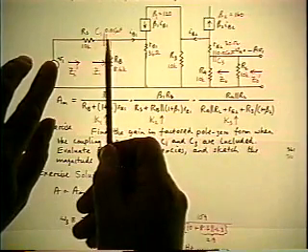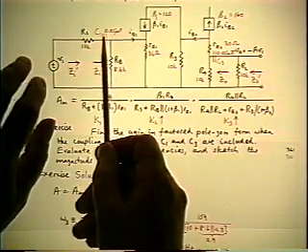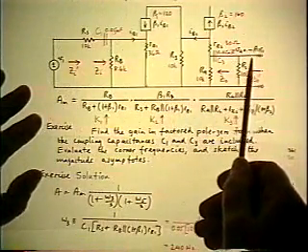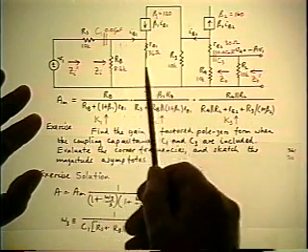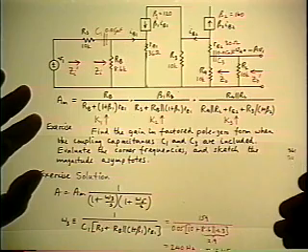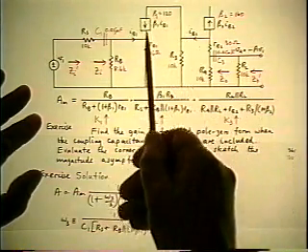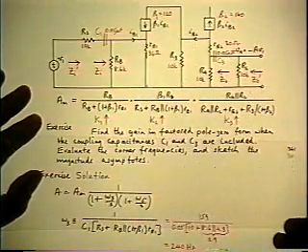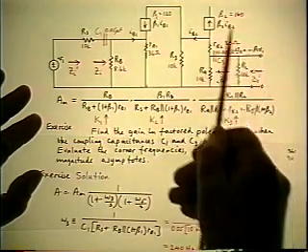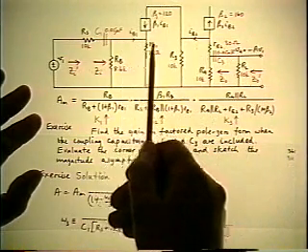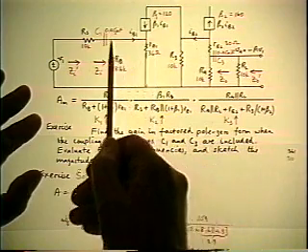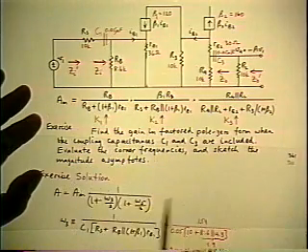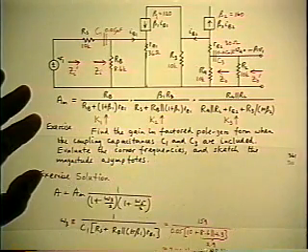And the Rn is found by replacing the capacitor with the independent source, restoring the V1, twiddling the two until the output nulls, and propagating the null back. Again, it doesn't matter how far away the output is, because it's going to propagate all the way back to the collector and the emitter and the base of the transistor, just as it did before the emitter follower was there. So nulled output propagates back to zero base current and to zero emitter current, therefore zero current in RB, therefore zero current through the second source, therefore Rn is infinite, and there is no zero that comes in the transfer function.